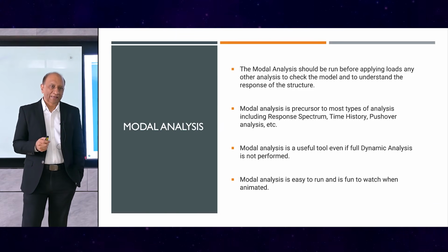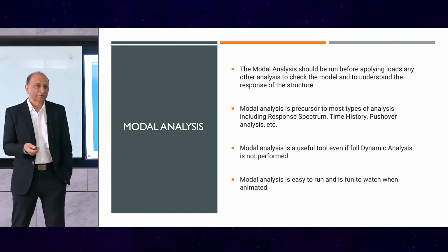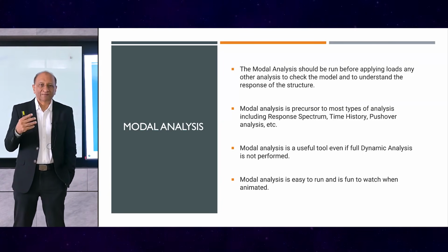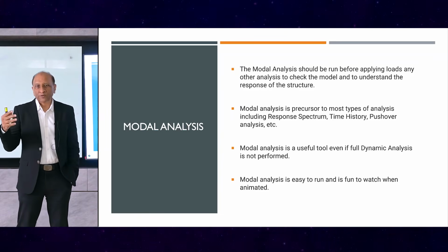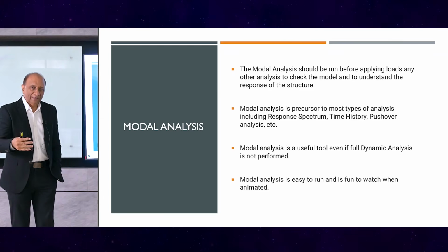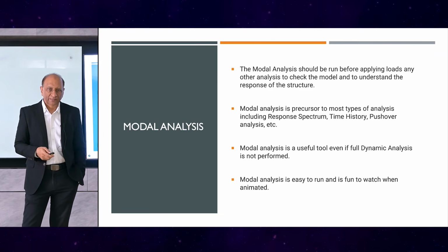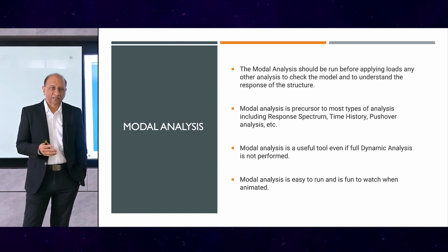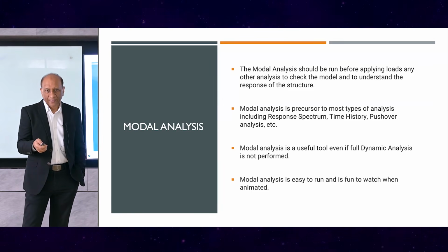run before anything else. We always recommend to our students and our colleagues here that if you're creating a model in ETABS or whatever software you're using, even before running the dead load, run the modal analysis first. Make sure that the properties are right, the structure is right, the model is right. If the model is right and the properties are not good, that means the structure is not good. So we need to go step by step to make sure that what we are dealing with is reasonably correct before we start applying loads and doing the rest. So modal analysis is a precursor to most of the analysis that we will do later: response spectrum, time history, everything, even wind. So we will look into that.